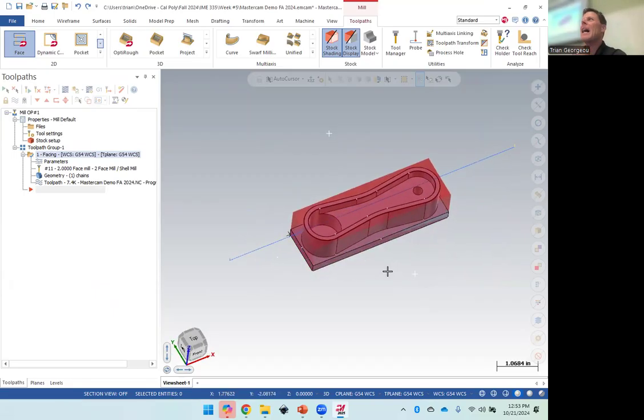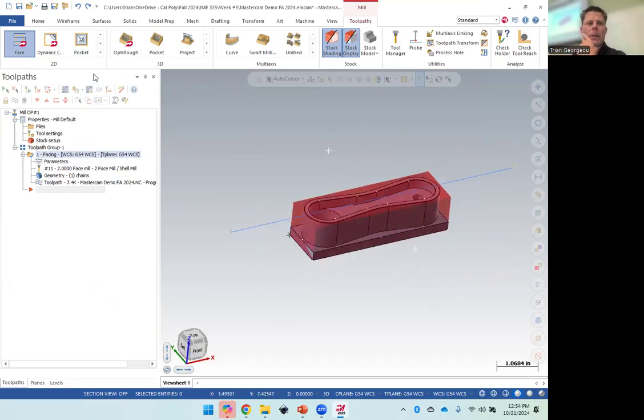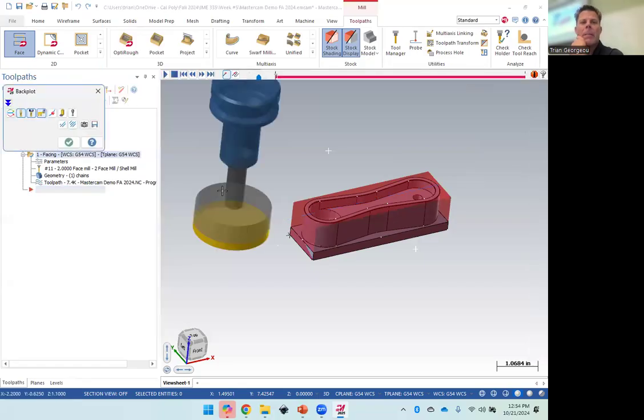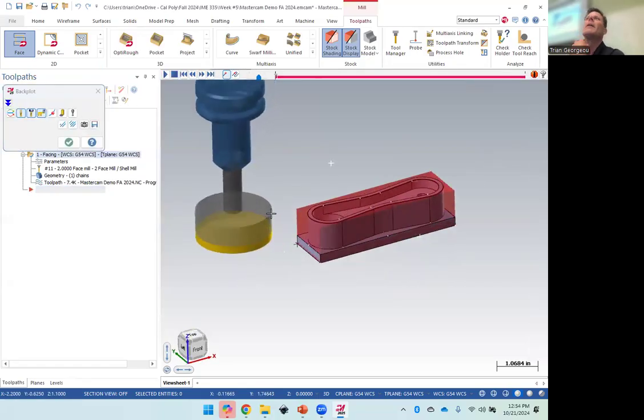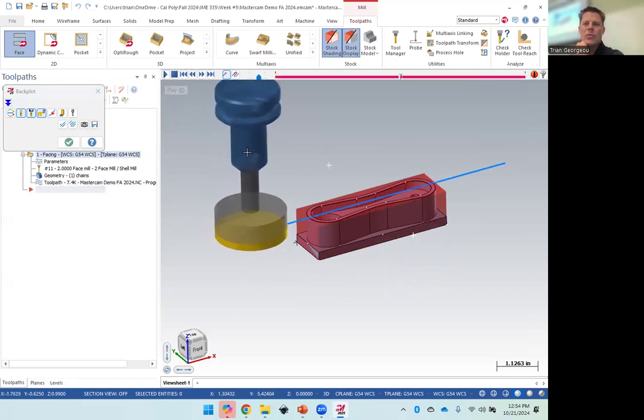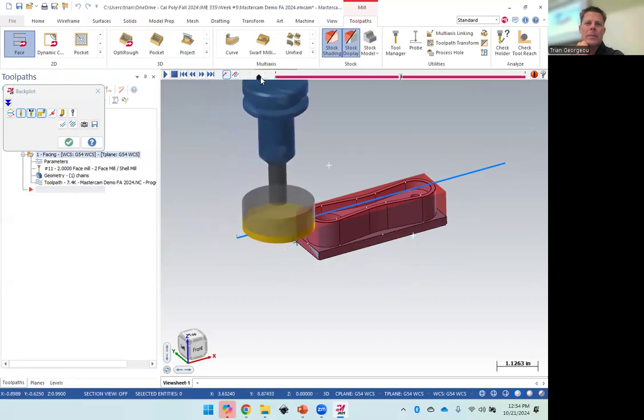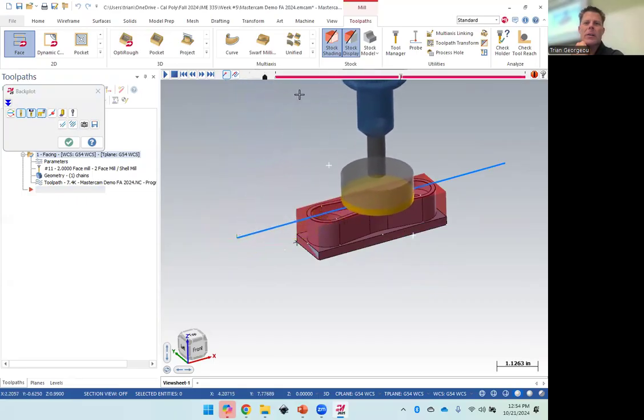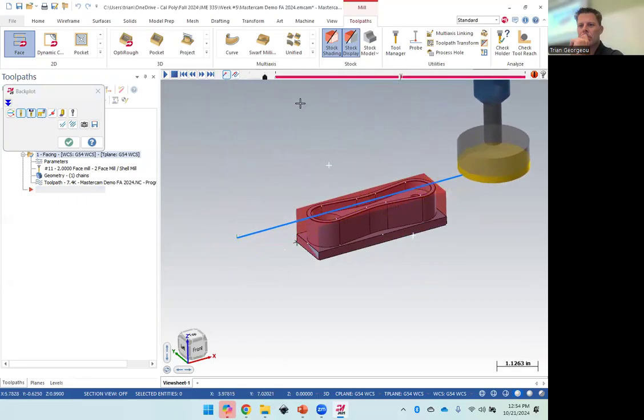So there's got to be a way I can check to see virtually if this looks good, right? It's called simulation. There are two ways to simulate in Mastercam. There is backplot. Me clicking on backplot brings in that sweet holder, right? And I press play. I'm going to go faster. There's a little speed slider right here. It's real touchy though. See that? So that was it.